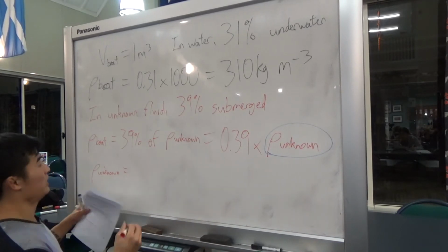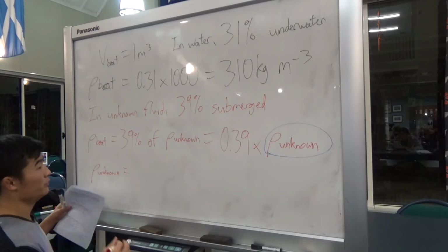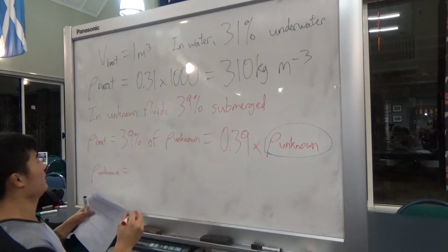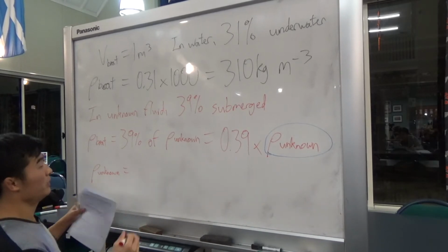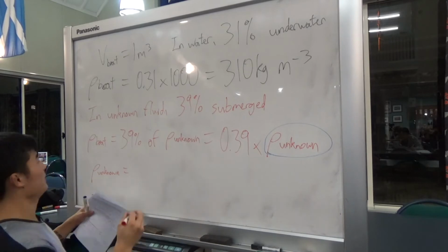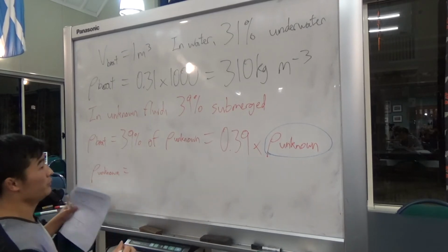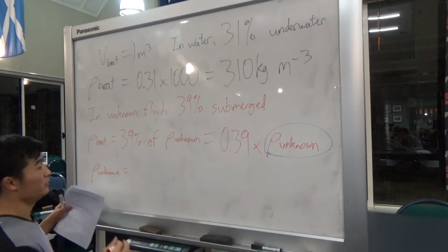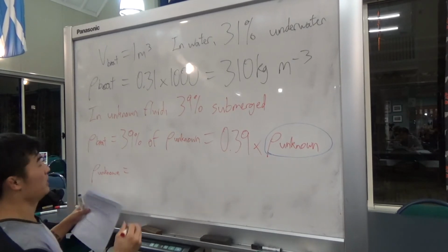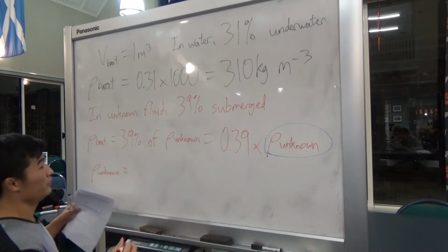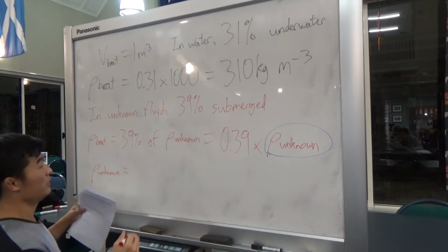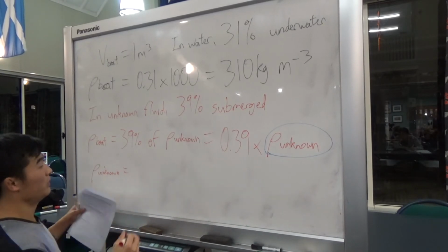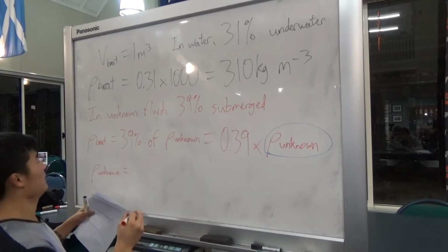So what we want is the volume of fluid. So we're going to rearrange this equation for just volume. So the change in volume is equal to area times velocity times time. So delta V is equal to the area, and we can use either one, because remember the flow rate at every point in the pipe is going to be the same.